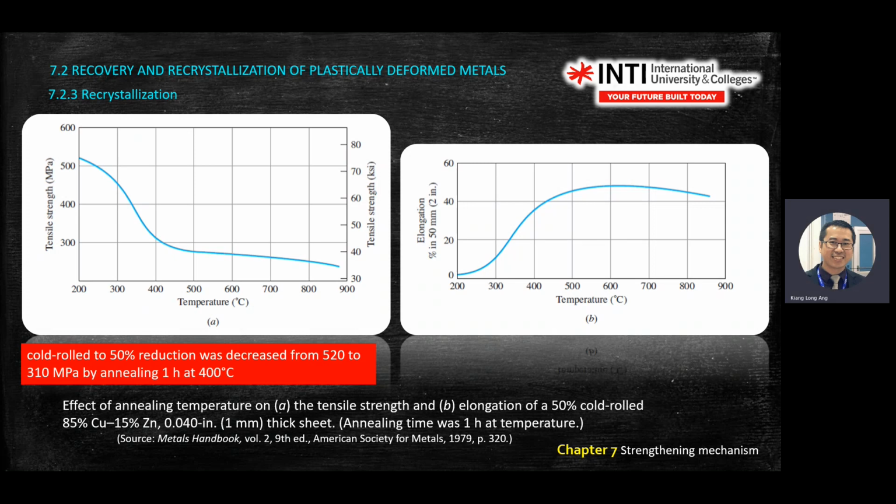Okay. What do I mean by tensile strength? Again, on the tensile graph, stress strain, you have a graph there. The maximum point is your tensile strength, or UTS. Maximum point, and 2%, or at the end of the elastic, is called yield strength. Yield strength, you can simplify by finding the last end.